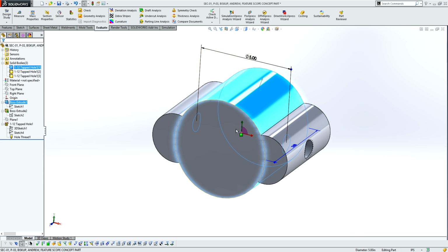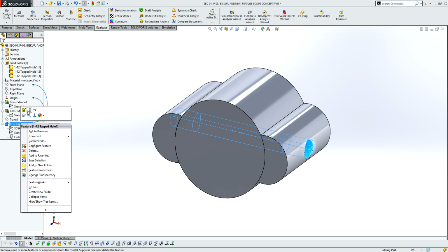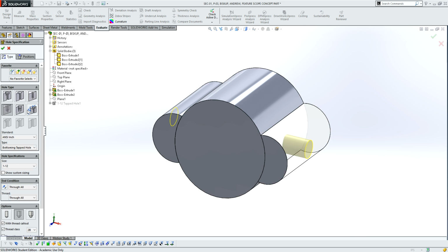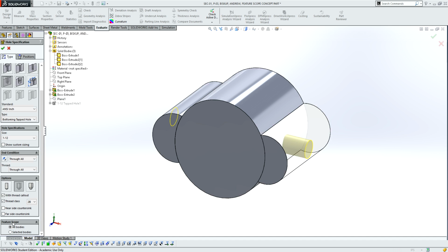So this is supposed to be solid, but currently we have a hole going all the way through it that's messing up our weight. So if you right click on the part, you edit your feature, you scroll down a little bit, you'll see that feature scope button. It'll say all bodies, like I explained a minute ago.